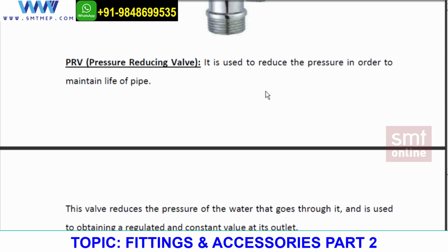So I'm cutting it at that moment only. So no doubt I'm maintaining a pressure which is prescribed by the standards or codes, that is as per IPC and UPC. I'll do an example also right now. First of all, let's see how it looks and where it is installed. I said it is installed to maintain the pressure in the line at less than 60 psi or 80 psi, and always remember it is only installed in the risers within high-rise buildings.